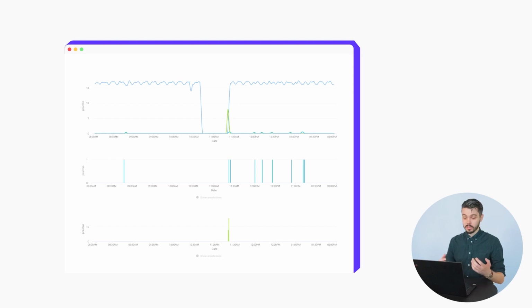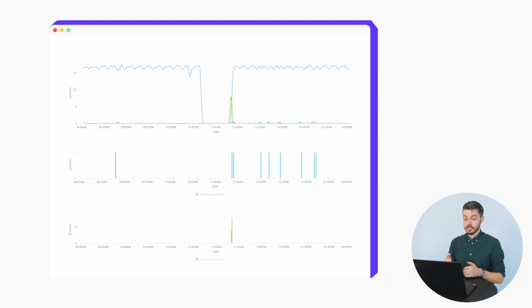Secondly, in our system, we can monitor the scrap you're producing on the line. This can be done in two ways. One, by adding external sensors on the line or copying from other sensors you have to monitor the scrap. So if you already have points on the line where products get taken off automatically or sensors are counting scrap, we can take these signals into Factbird, and as you can see here, we can actually monitor each iteration of these signals so that you can actually understand, right, we've lost X amount for scrap reason A and X amount for scrap reason B. So you can start to drill down and narrow down the real quality issues on your line.